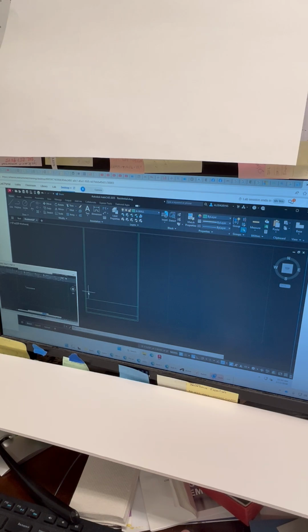Every other dimension is different: 3 foot 7.5, 2 foot 6, 6 inches, 2 foot 10. The 3.5 only repeats twice because we're creating two walls. So for your default dimension, I'm going to have you put in 3.5 for 3.5 inches.